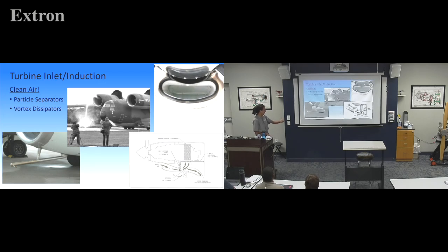What type of turbine engine does use an inlet screen? PT6. So smaller turboprops don't have as massive airflow, and you can have very coarse mesh screen like this to cover the inlet. And oh, here's bonus. Anybody remember anything unique about how Pratt & Whitney makes the size of their mesh? Exactly, to prevent any of their hardware from getting ingested. So if hardware's in there, it's not theirs, you did something naughty.